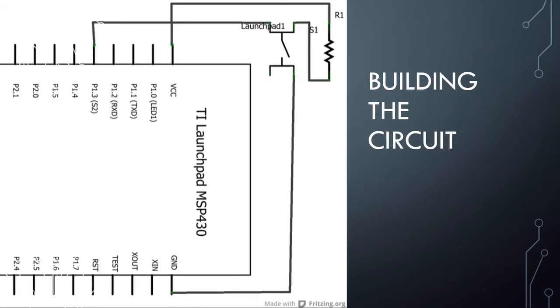What we just looked at was a picture representation of your push button setup. This is just a circuit representation. You can see we have our push button here, and it kind of looks like the representation for a switch. When it's open, it's not being pressed, so there's no current flowing. If it's closed, the current can flow. We have our 4 corners here.